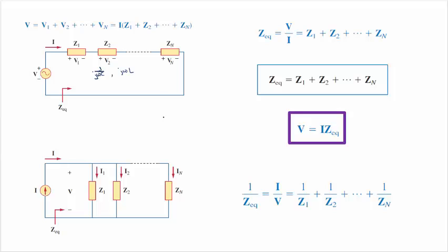And you'll have the values, and I don't care if it's in series or in parallel. For each component you're going to write down what its ohms are. It's either going to be a resistance R, or a resistance that varies with frequency, so it's going to be 1 divided by j omega C, or j omega L. And so at the frequency of interest, you will have the ohms of each element. And then you can generically replace each element with a block, as done here. And then all of our circuit analysis tools apply.